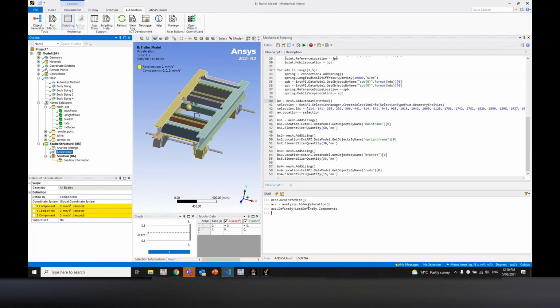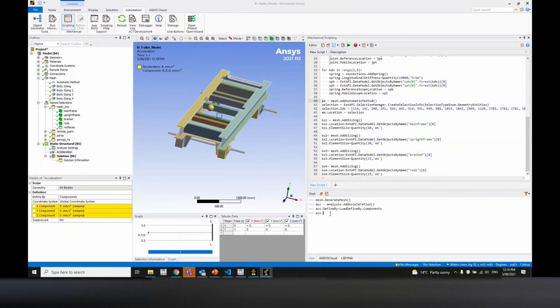And now what I want to do is change the Y component to 2 millimeters per second. This is going to be a little different. What people would normally think would be, I'm just going to do this, right? Component equals quantity bracket open. Say I want 2, comma, it's acceleration, so it's millimeter per second squared. So second to the -2. People would think that'll work. Unfortunately, I think second is sec. Sorry. Actually, it wouldn't work. I can try it. There you go.